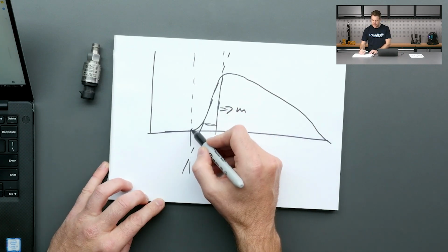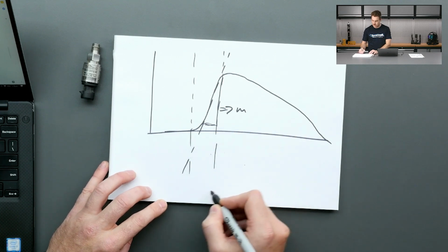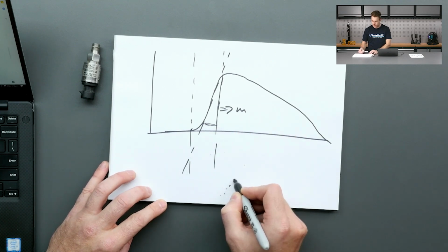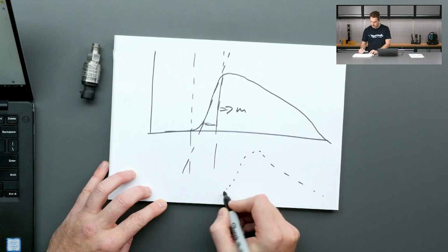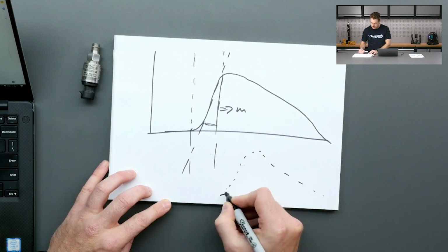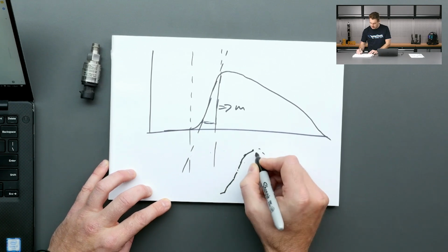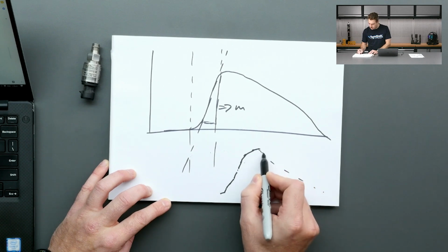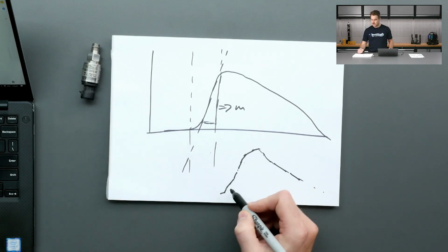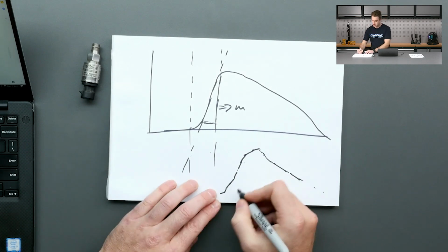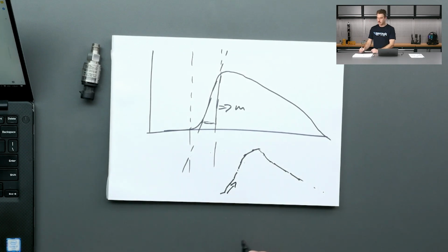But essentially, what the software is actually doing is, if I was to bring this down to the actual points that this is looking at, between each one of these points, it's taking the slope between each one of them. Now, what's different you'll see is when we're applying the brakes as opposed to when we're releasing the brakes, is that each one of these little slopes is positive. It's going in this direction when we're applying, and it's going negative, going in this direction, when we're releasing the brake. So if we're looking at brake aggression, we only want to calculate it when we're applying it. So for a start, we say only calculate when the derivative is positive.